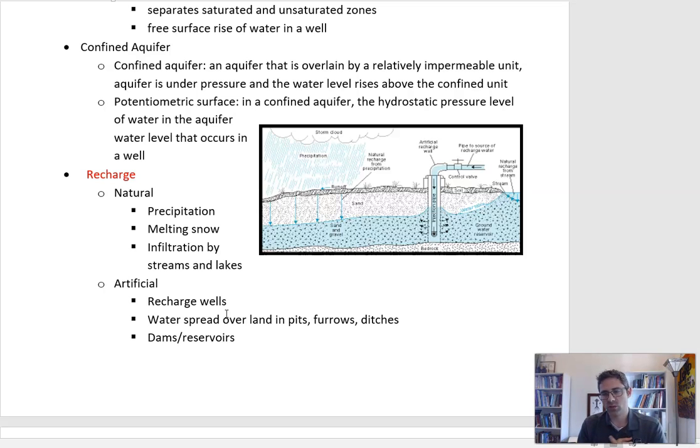There's places where we want to try to resist saltwater intrusion, and so sometimes we pump fresh water in near the ocean to keep saltwater from infiltrating down and into our aquifer. And so there can be artificial recharge wells there too. Reservoirs, so if I build a dam and a reservoir fills up behind it, that's artificial recharge where maybe before the stream that was going through would only have a limited recharge. Now I have a reservoir there year round that's probably infiltrating some amount of water into the aquifer all the time.